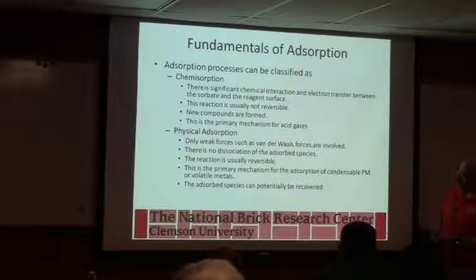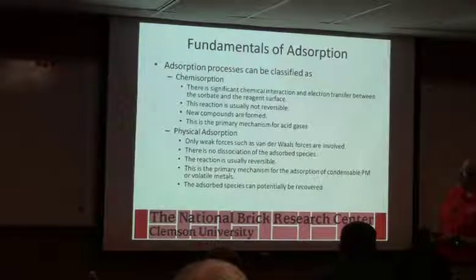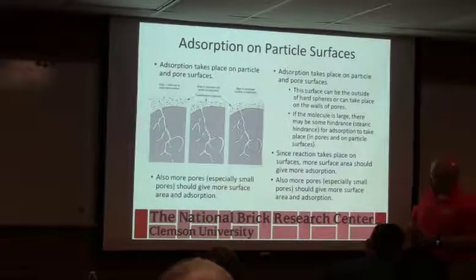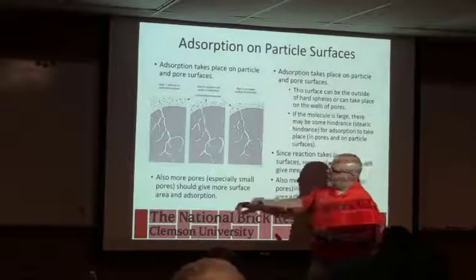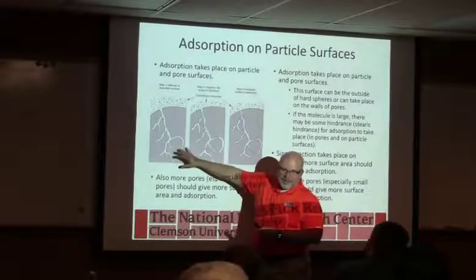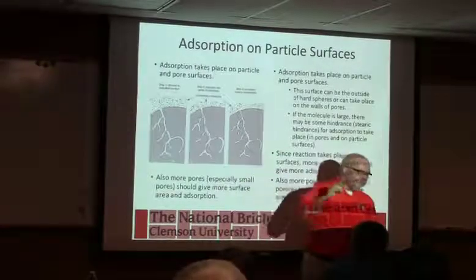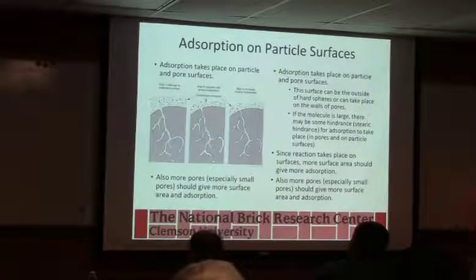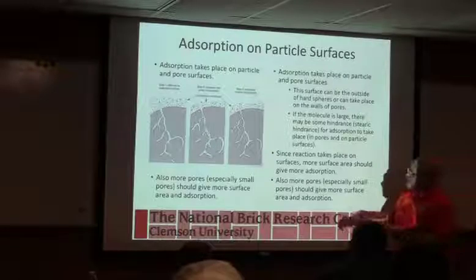It will hold on to organics, and sometimes it'll hold on to metals with that physical absorption. So in your scrubber reagent, ideally you've got something, and this is a balance. You want something that's got what we call surface area or porosity, because the surface is where this stuff reacts.